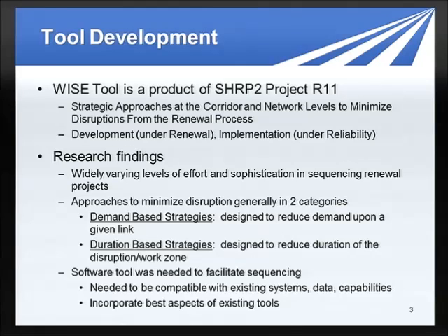And what came out of that too is there's a whole long list of strategies you could use on any road project to help manage the impacts. You've got contracting, you've got accelerating construction, you've got using some prefabricated materials. You've got law enforcement, for example, to manage certain kinds of impacts. You've got speed management, things like that. So you've got a whole range of types of strategies, and it would be best to group them into two areas based on feedback from some panels that were convened for this.